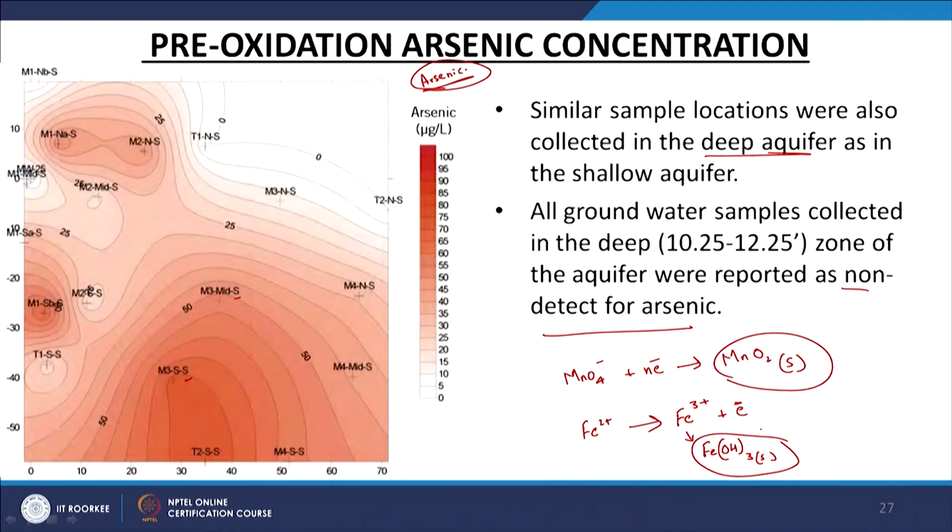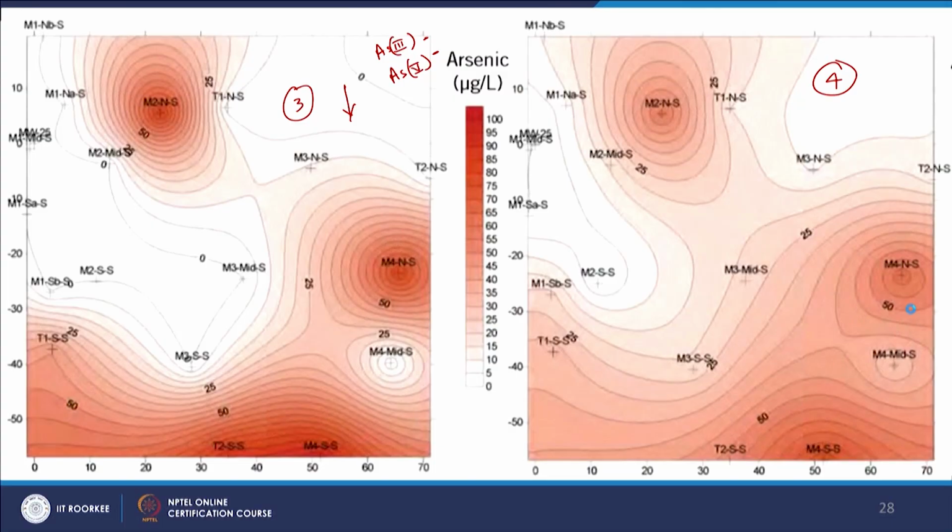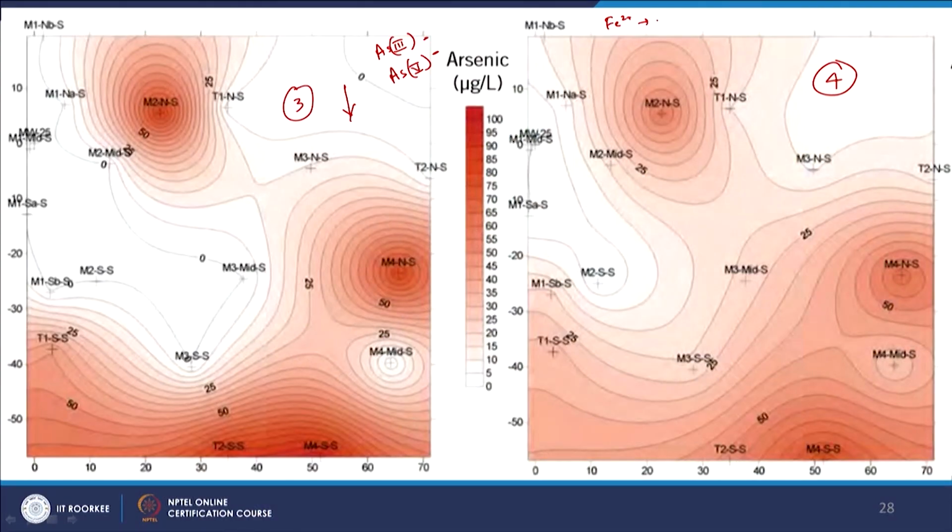So, as these particular solids precipitate out, arsenic will be adsorbed onto them, and you will have something called co-precipitation. So, this is one mechanism by which some of the heavy metals are going to be removed, and in this case I believe that is what happened with arsenic, as in ferric iron and also manganese, after the relevant reaction, ferric iron from ferrous,